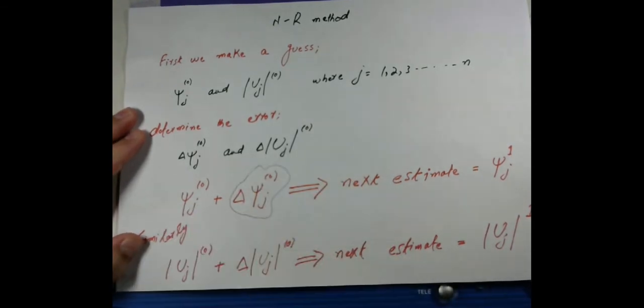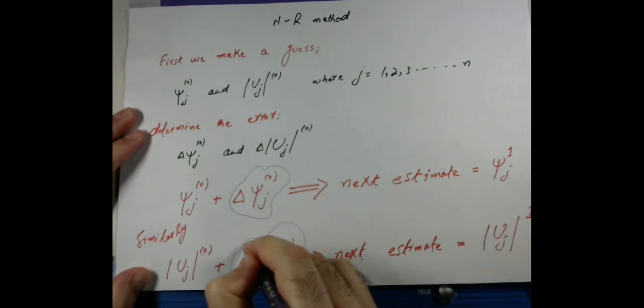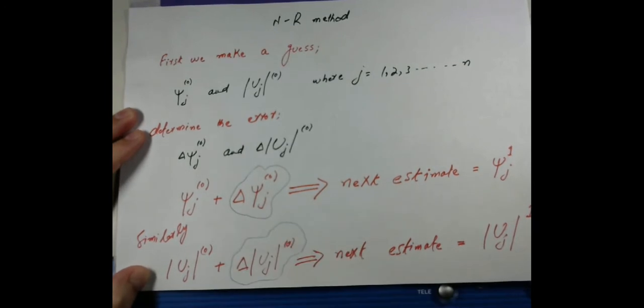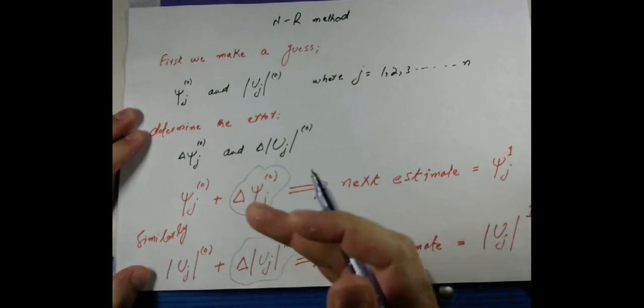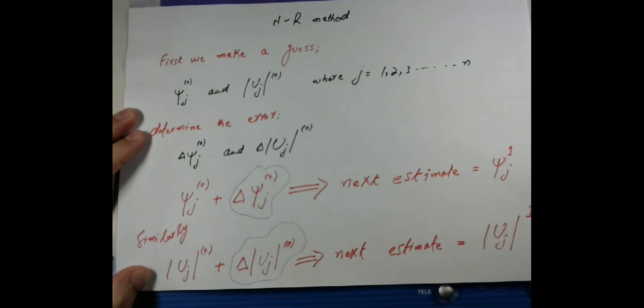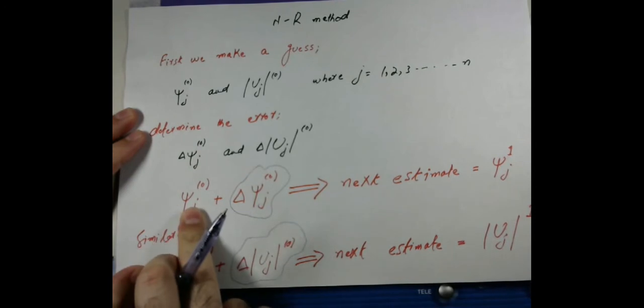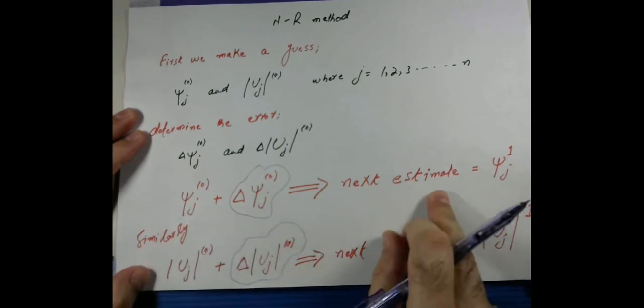We know that in the flat start how we guess these values, but the important question is how to determine the error. So these are the errors in the first estimate, and now we will try to determine the general form to find the error in the first estimate. And once we find that, we add it to the first estimate, and then we get the next estimate.